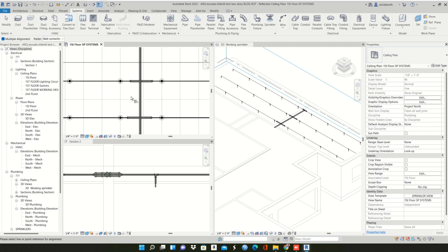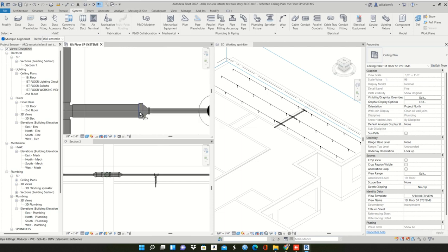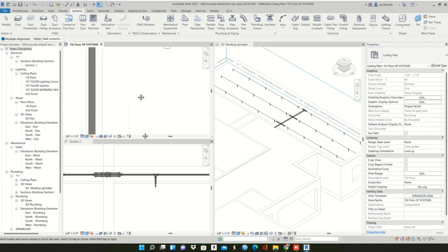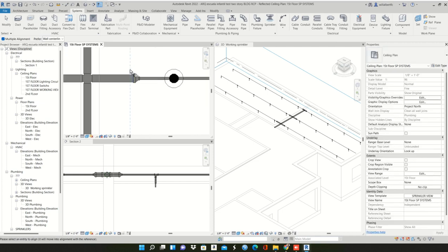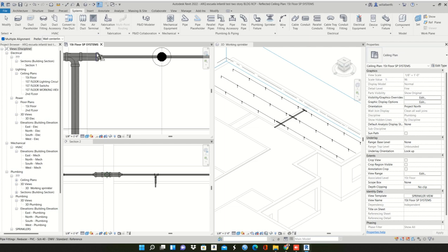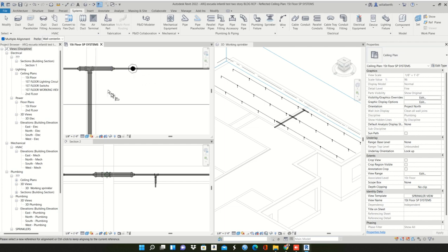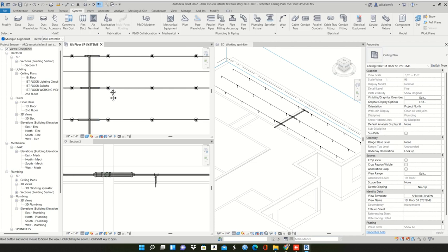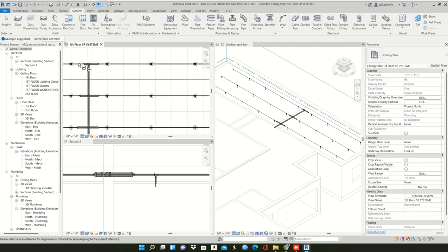Now go to your pipe and select a face. We're going to tell Revit I want all my reductions to be at the same distance. So we select this one and it's okay. And we select this one and it's more beautiful because you have the same distance here. It's not like this is bigger, this is longer. It's really symmetric. Yes. So do the same here.